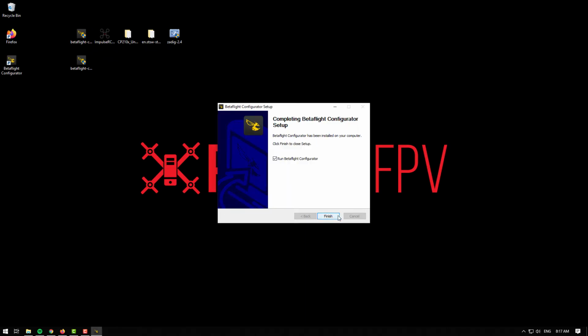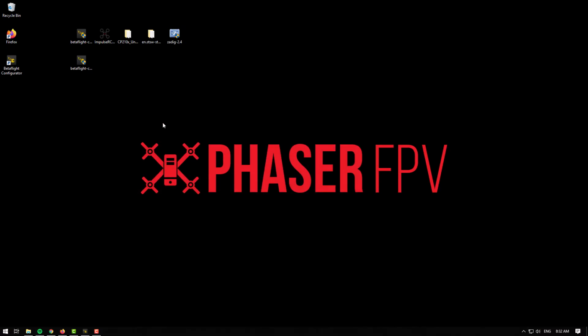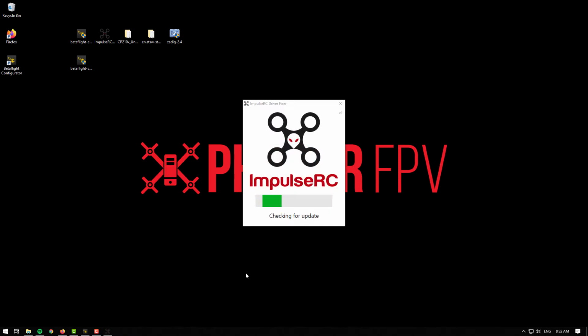When Betaflight finishes installing, select Run Betaflight Configurator and hit Finish. Upon opening Betaflight, you'll notice we can't select a device to connect to just yet. We need to install our drivers. You can download them all manually here from the home page if need be, otherwise run the Impulse RC Driver Fixer that we downloaded earlier. When the installation is complete, if you see a green success bar, pause the video and continue to flashing your flight controller. If not, continue watching and I'll show you how to install the drivers manually.